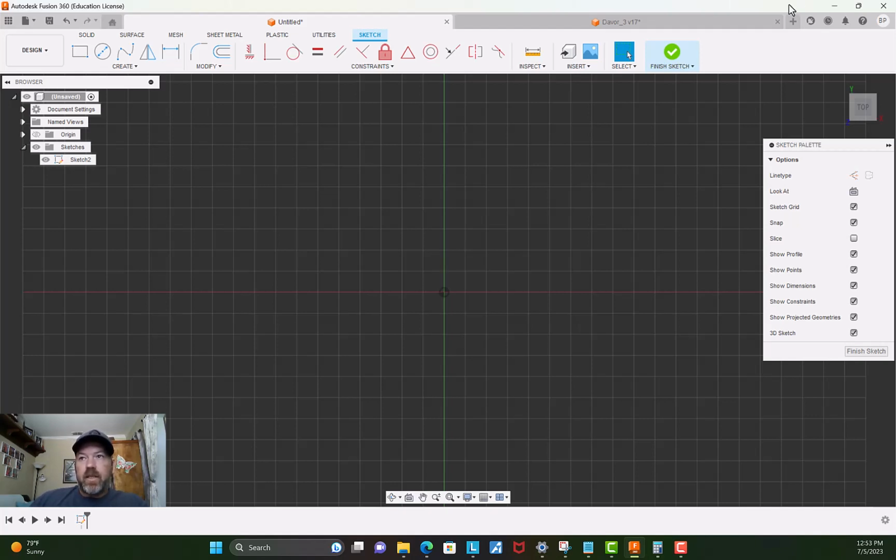To calculate that, it's actually pretty simple. The tapers per inch is just your large diameter minus your small diameter divided by the length. And if you want to get the taper angle, we need a little bit of trig, and it's basically just take the arctan of whatever your tapers per inch is divided by 2.